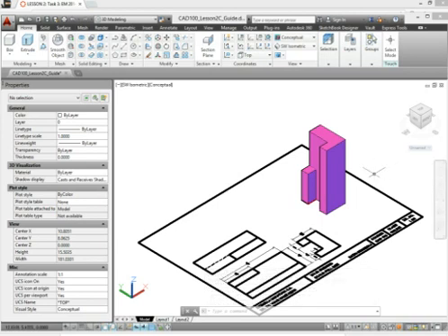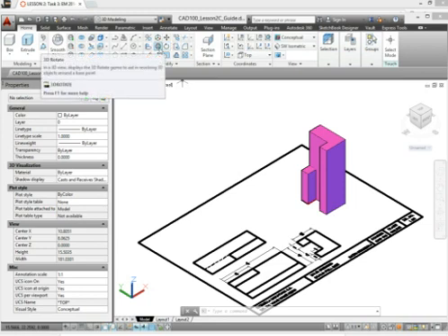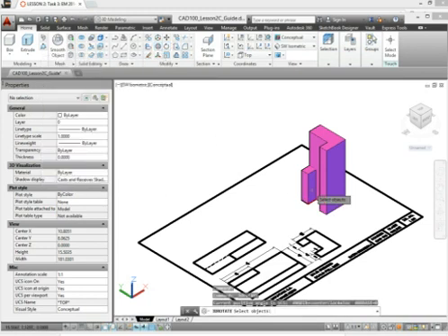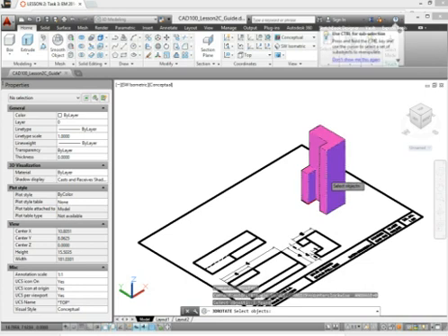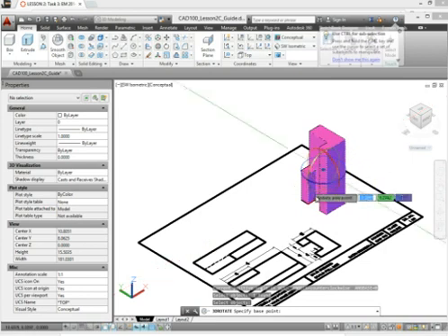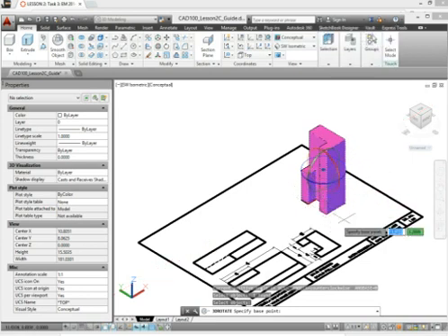Alright, this is an addendum. How to rotate your blocks if you are interested, and how to move them. Pick this command here called 3D Rotate. Pick an object and hit enter. The base point indicates where on the feature you want to work from. You could pick basically anywhere. I'm going to pick here because of the way we're going to rotate it.